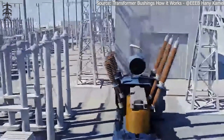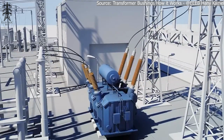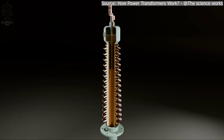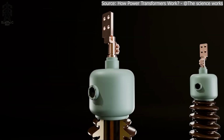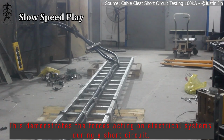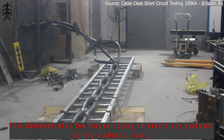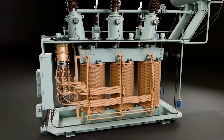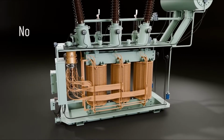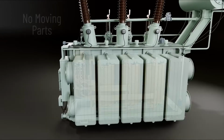Bushing failure is the next common failure for a transformer and fails in much the same ways as the insulation breakdown, since they're also filled with oil, such as by water ingress, internal degradation, partial discharge and thermal runaway. Winding failure is another form of failure in which short circuits can occur, leading to inter-turn faults, or complete failure, and are also caused by thermal aging, mechanical stress from through faults, and poor manufacturing, which can lead to transformers failing in the first few years of operation, rather than 30 to 50 years later.